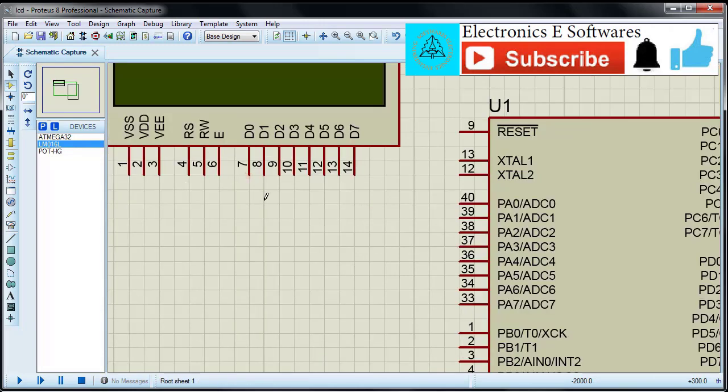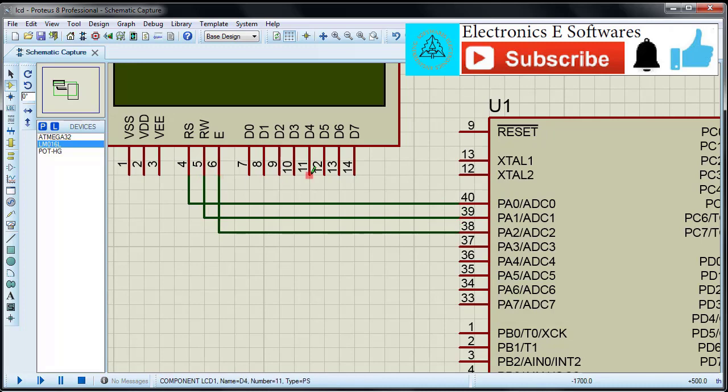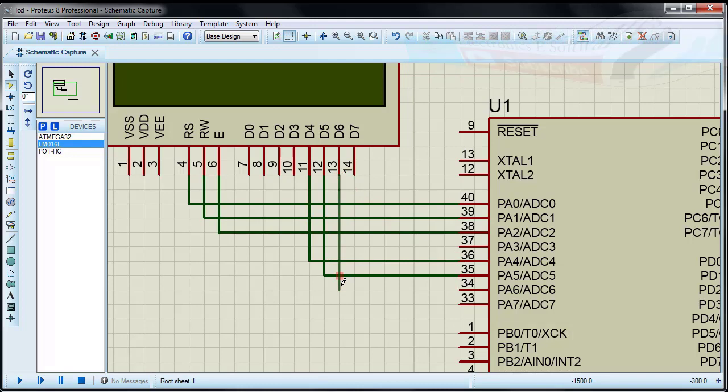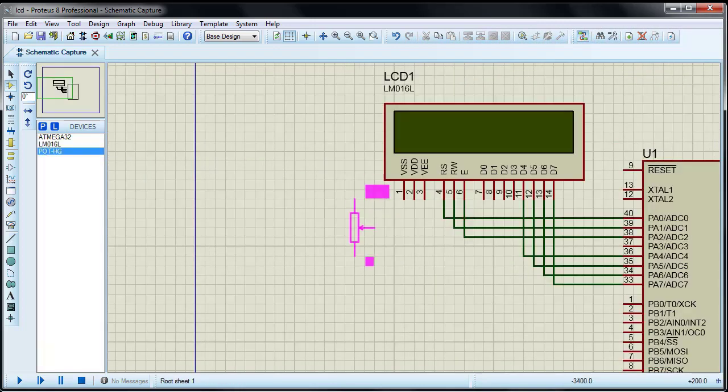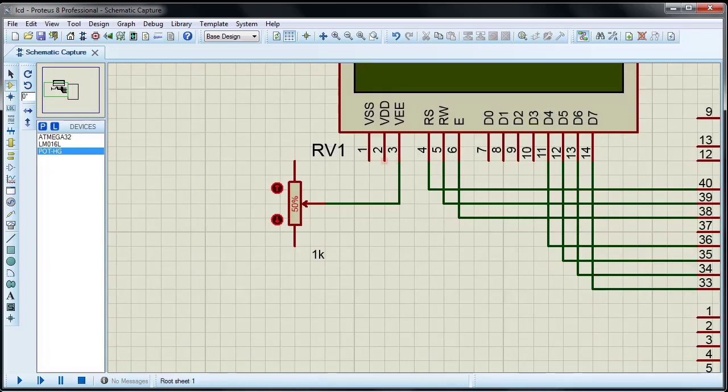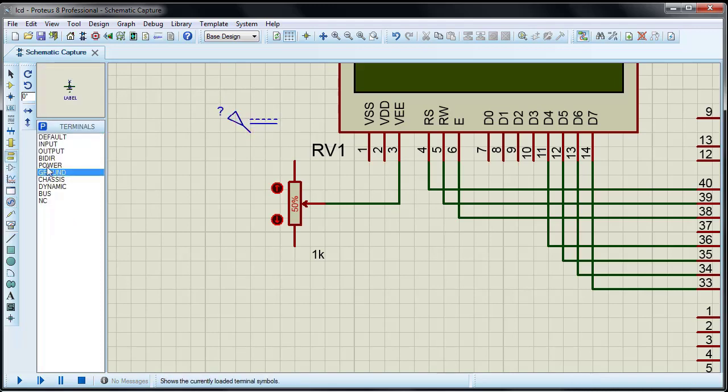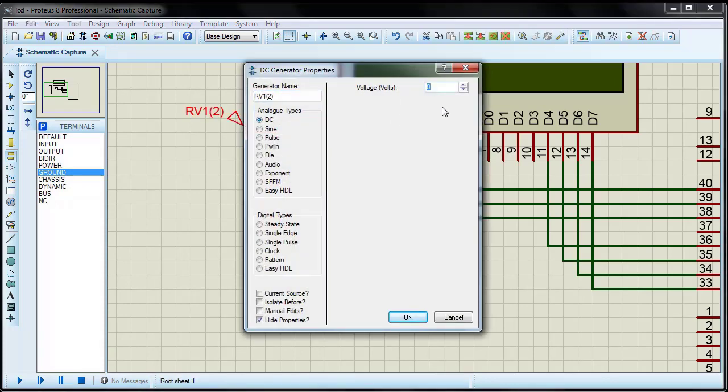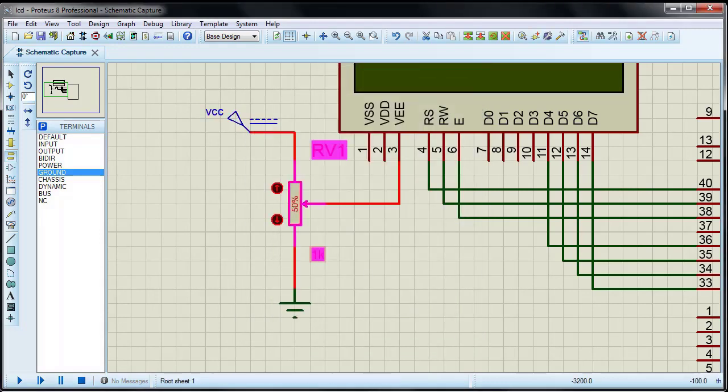Follow the default connection of CodeVision, and connect the LCD to port A. CodeVision functions support 4-wire communication. Connect the pins according to the datasheet and the 4-bit connection. The power supply is 5 volts, and the LCD pins 15 and 16 are hidden in Proteus.